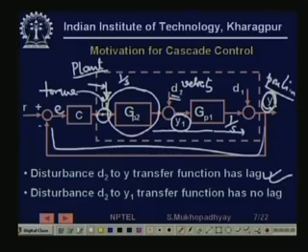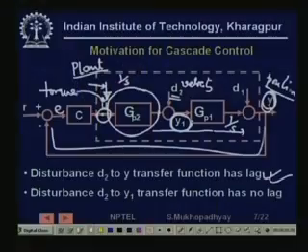So now this is an observation. Here is an intermediate variable which we are not using, maybe it could be measured, very simply. For example, in the case of the cooling reactor, suppose we could measure the jacket temperature, why not? That involves simply putting a temperature sensor.